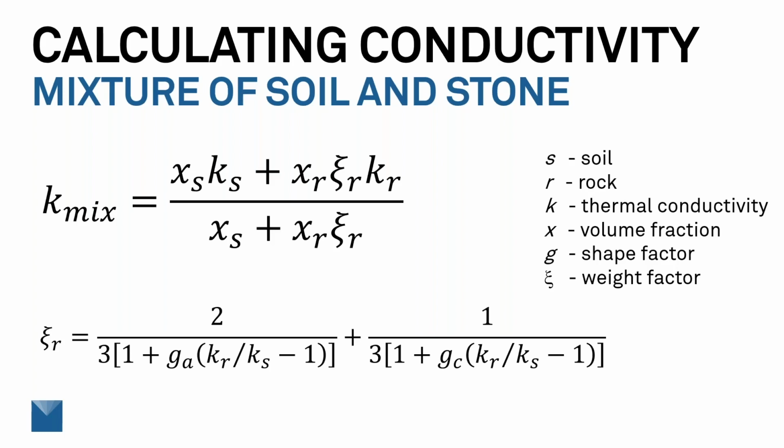Well, that's always a challenge to make these measurements, the contact resistance. What we choose is a grease that has a thermal conductivity that's high compared to the rock, and then we try to make the hole fit as tightly as we can. And if we get those things right, then that grease assures us of a good thermal conductivity measurement.